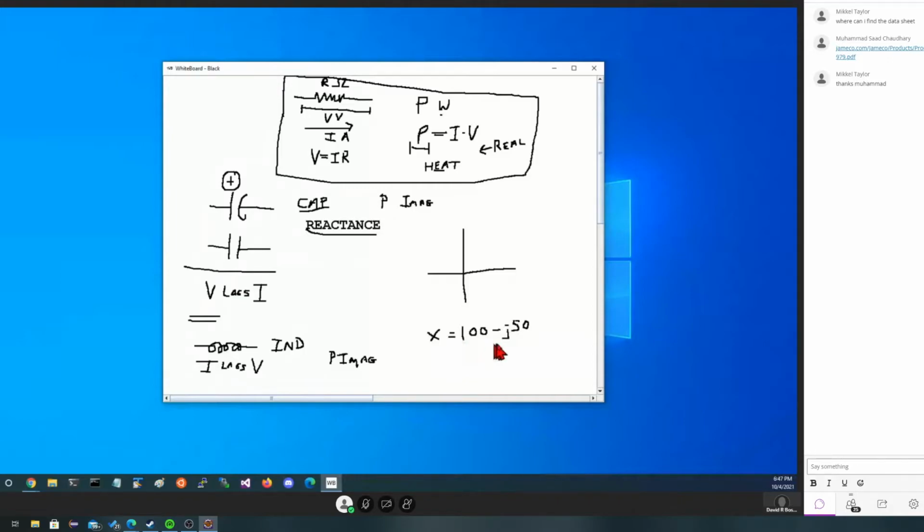So this is a number which we call the impedance of a particular set of elements. The impedance is a complex number with a real part. The real part is called the resistance. And the imaginary part is called the reactance. Now, on the complex number plane, if I have something that's a pure resistance, which is all we've been working with so far, it lies right along that axis. So if we got a 10K ohm resistor, this line would be 10,000 long. We got a 100 ohm resistor, that's 100 long.